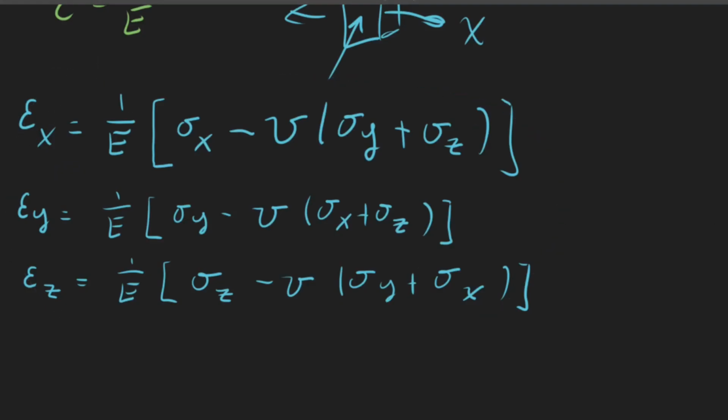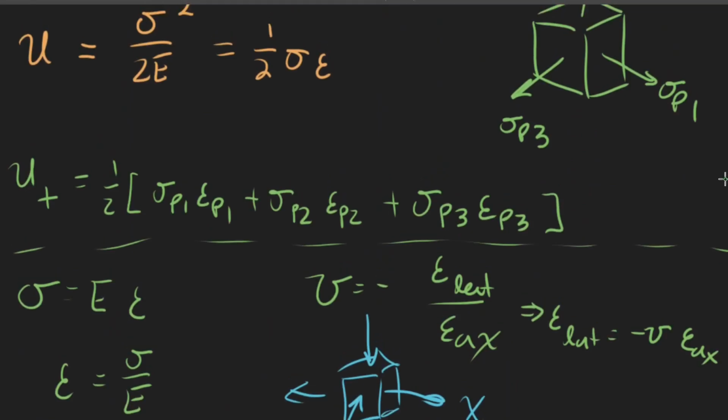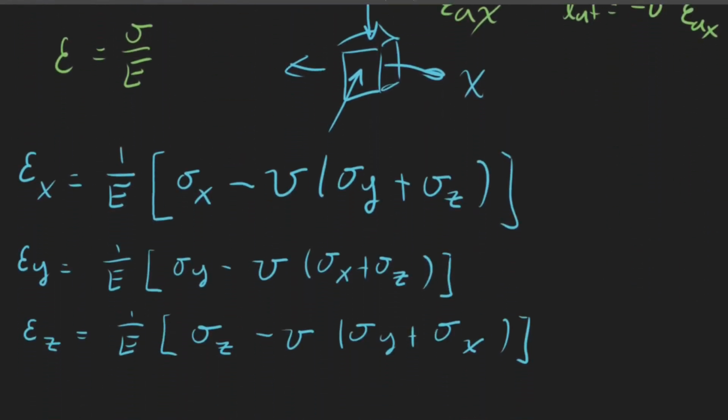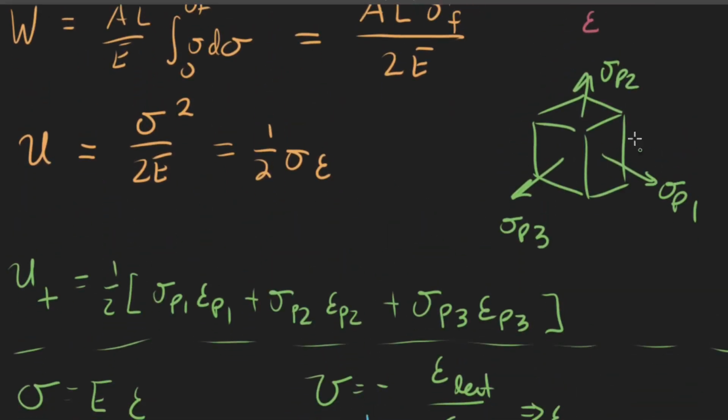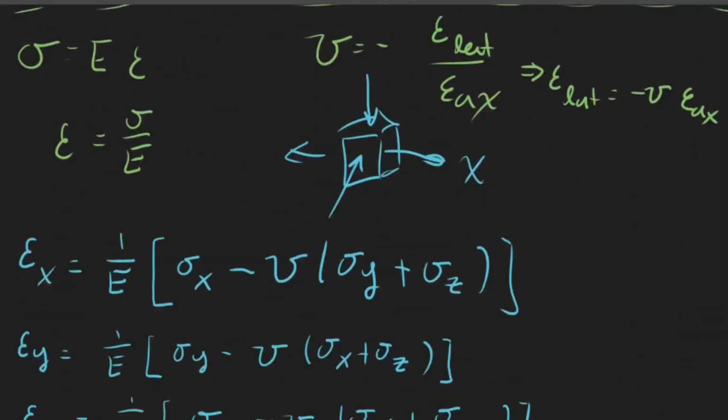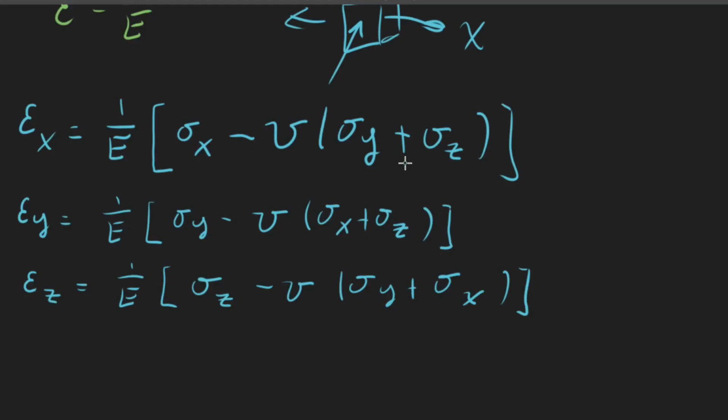So now what we can do is take all of these equations that we have right here and plug them into our distortion energy equation right here, where I should be clear that x, y, and z are just some general axes, but that could also correspond to P1, P2, and P3, because there's nothing here that actually depends on a specific axis. The only thing that matters is that they're all mutually perpendicular, which they are, and that this x-axis, whichever strain direction we're looking at, is in the same direction as the stress, except for these two, which are going to be perpendicular.